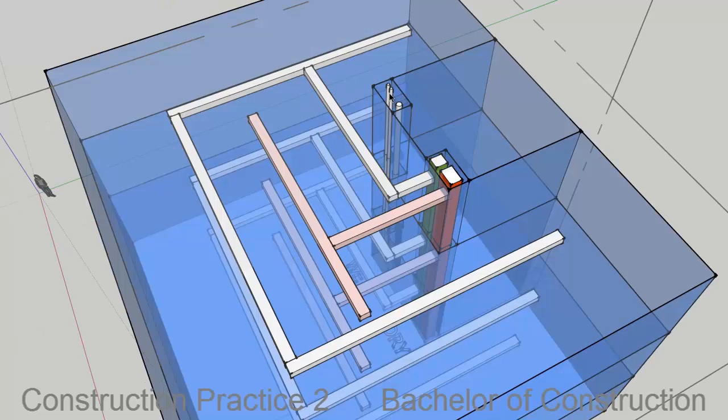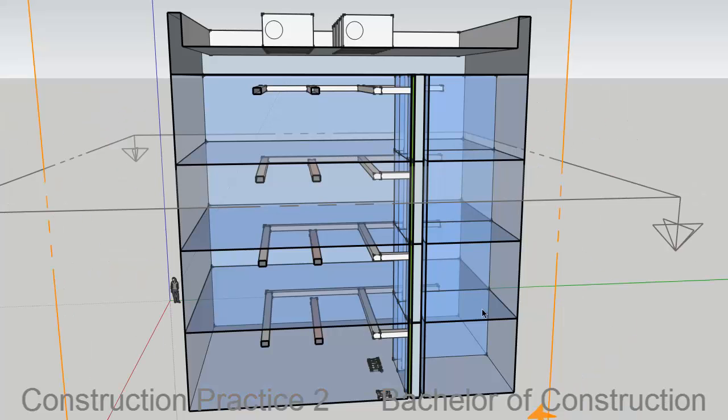If we look, for example, at the installation of fire services, we would see that we would have a vertical riser coming up through this duct, and then the duct would branch off and the fire sprinklers would be attached throughout. The reason I haven't shown all of this is it would be a very complicated diagram. So what I've done is just show the air conditioning as a concept here. This cross section shows how the central service duct feeds the main air conditioning supply and extract up and down the building with the branches at the different levels.